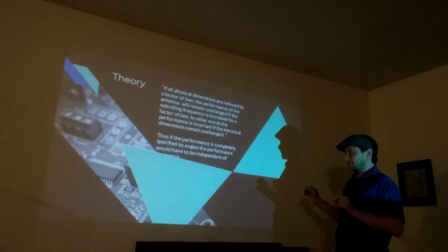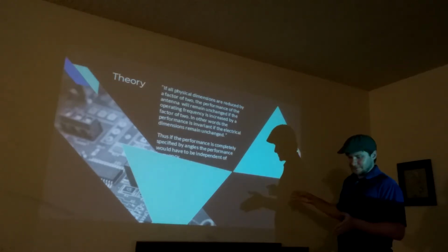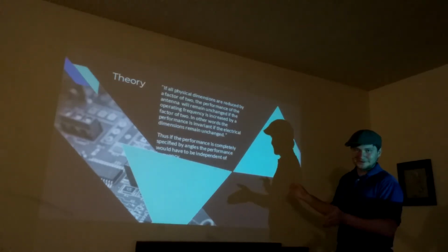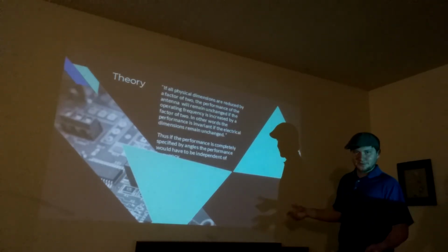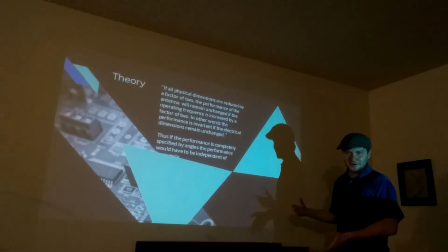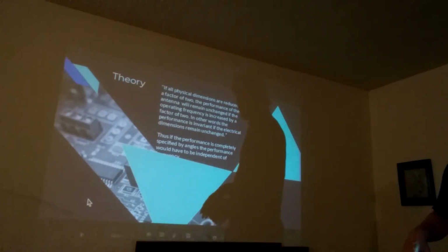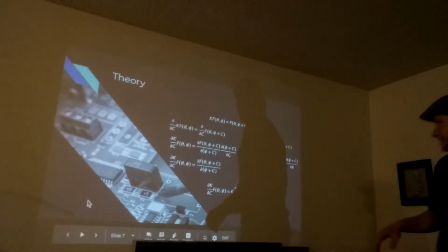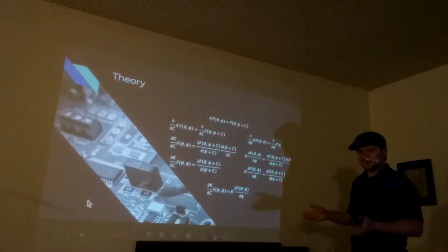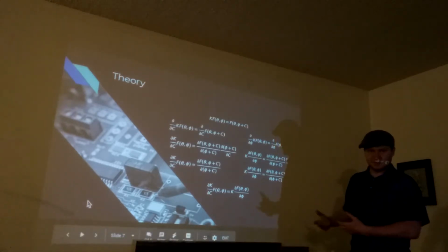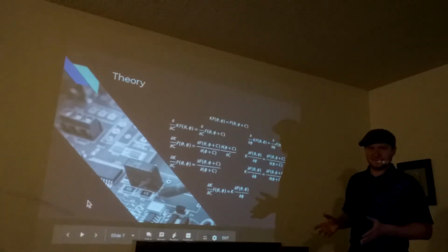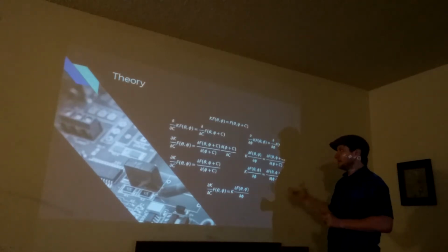And for the bow tie antenna, that impedance can be determined by the elliptic integral, which is just another integral, and we could use numerical software, or a numerical method, to evaluate that. So far, these types of antennas seem to have met all of my design criteria that I was going for, which made them seem like a good choice as intended to design.